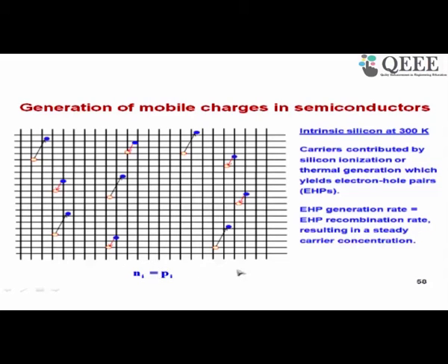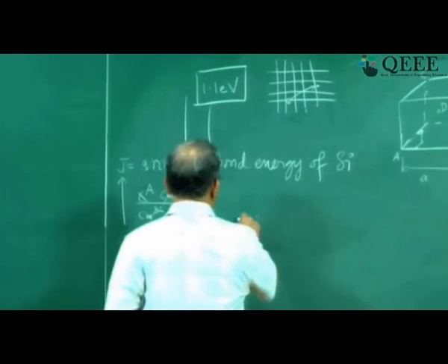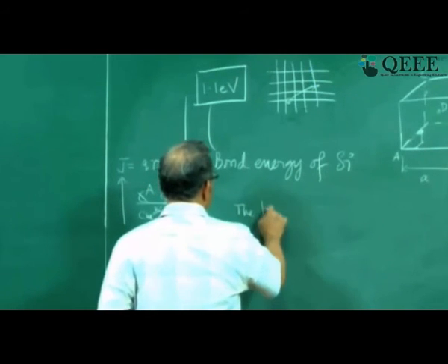Now let us look at this positive charge a little bit, or the vacancy. Why the vacancy acts like a mobile carrier or mobile charge of positive polarity. It is easy for us to appreciate how the free electrons will contribute to current. When you apply an electric field, the free electrons can move, right? But how do the vacancies move? The hole or the vacancy is like a bubble in a liquid. This is the bubble analogy of a hole.